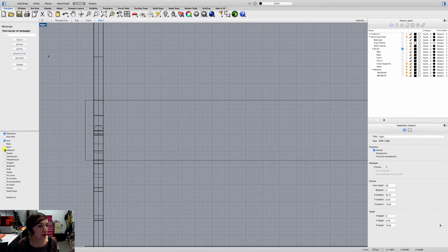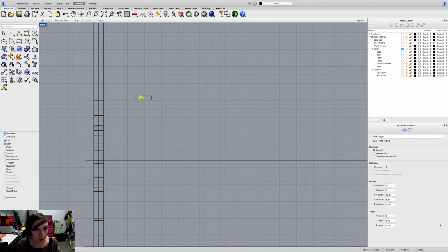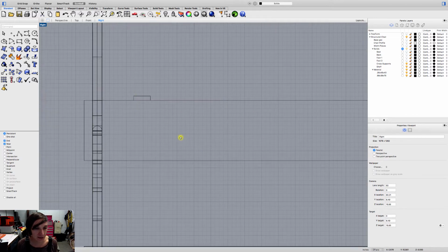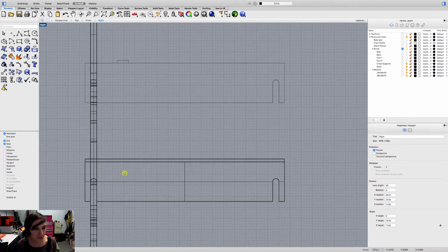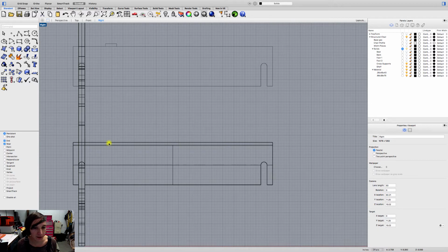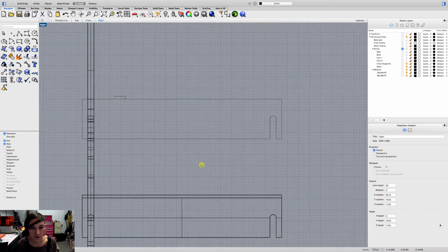Let's see here. I'm going to do near snap, and maybe they're just going to be 1 inch long, but only 0.26 inches tall. My goal is to add this solid to this face or that block, and then remove that hole from the top seat, and also remove that same kind of hole down here on the shelf.